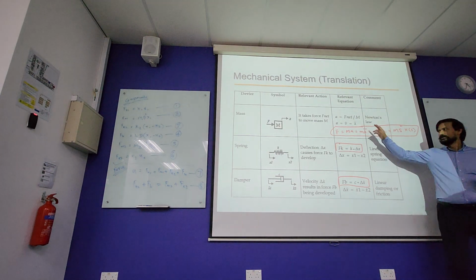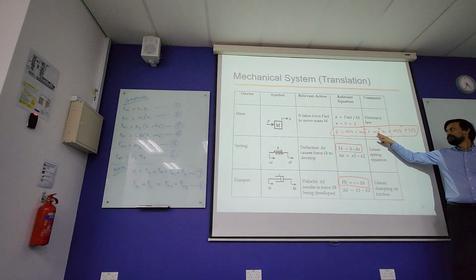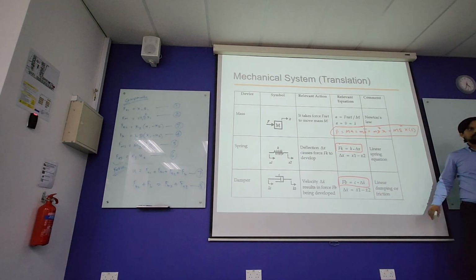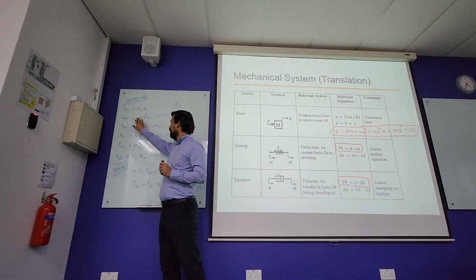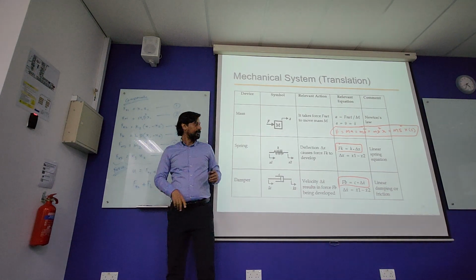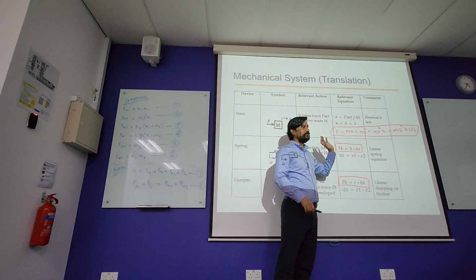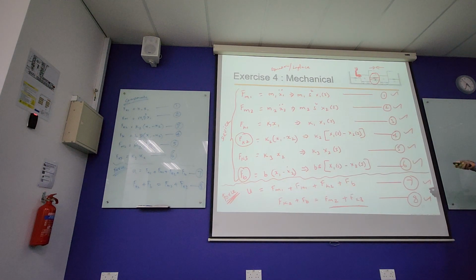One thing to say: when you talk about mass, you have d square. So very clearly keep it. When you say mass is d square, damper is d. So damper is 1d, you need to put it. So mass is d square, whereas the damper is 1d, velocity. Whereas the spring is very simple, x1 minus x2. So one is d square, one is d, one is normal. So that's the 3 components. No matter how many components are combined in the system, it is basically all these 3 components.